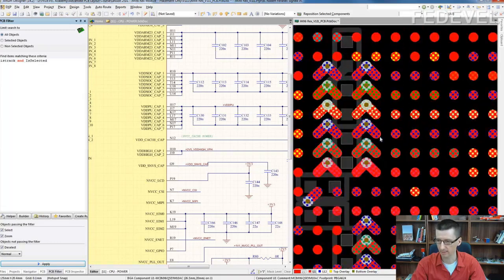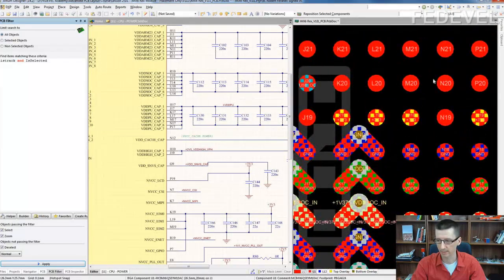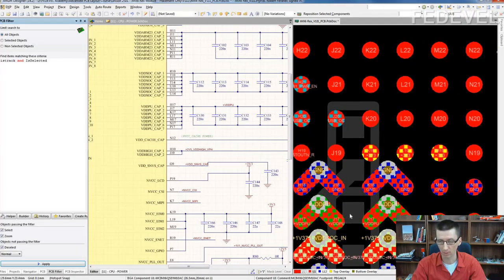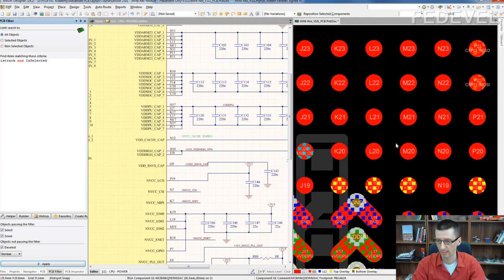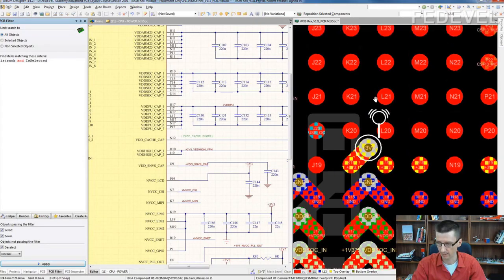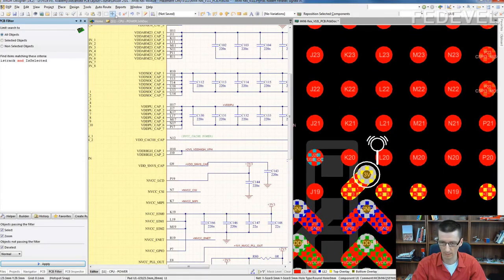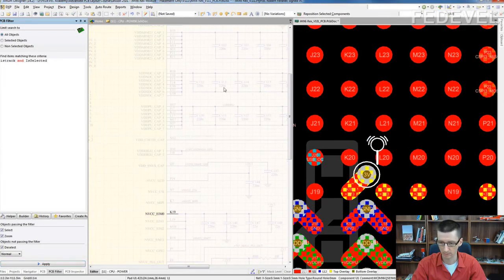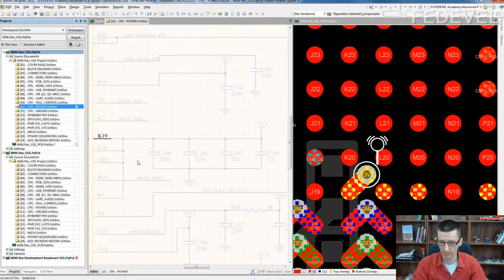Luckily, on the other side, there are unconnected nets, unconnected paths. So if you need space, you can go this way, here, and place decoupling capacitors here. That's really useful because, for example, for these pins, if we place a via here, and we will find what capacitor goes there, this one.